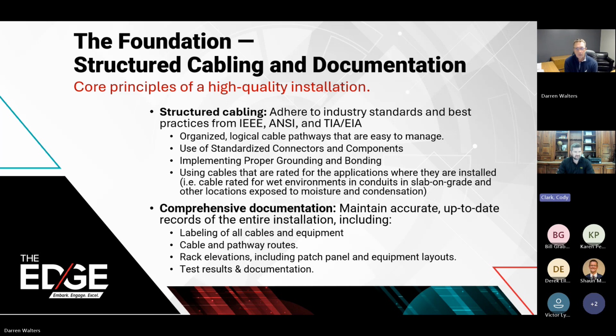A couple of the core pieces of having a good installation and high performance quality system is structured cabling. We need to adhere to the industry standards and best practices from the IEEE, ANSI, TIA, and EIA. A couple of those items are organized pathways, logical cable pathways that are easy to manage, making sure that we keep clearances for access to those pathways for future use and maintenance, and separating away from things that cause interference that's going to negatively impact the performance of our system.